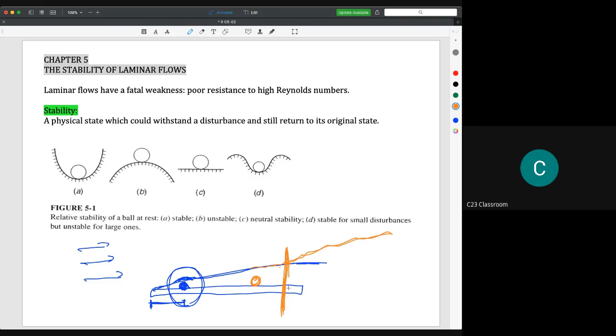Maybe because this is very near to the transition area, which is here, after the flow passes this wire, it will change into turbulence. So by adding the wire here, we could make the turbulent boundary layer appear a little faster compared to the common situation.